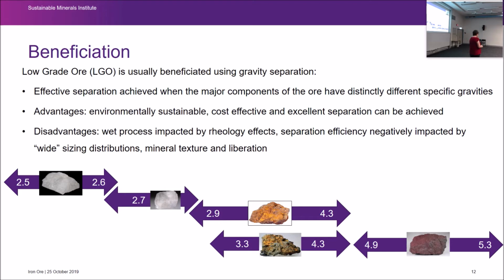So to illustrate, hematite would have a specific gravity in that range, where on the opposite end of the curve, your quartz, a silica oxide bearing mineral, is about 2.5 to 2.6. That difference between that mineral specific gravity and the one you're interested in is what affects your separation. As your ore quality changes, though, the difference between these two ends shrinks, and separation becomes more difficult.